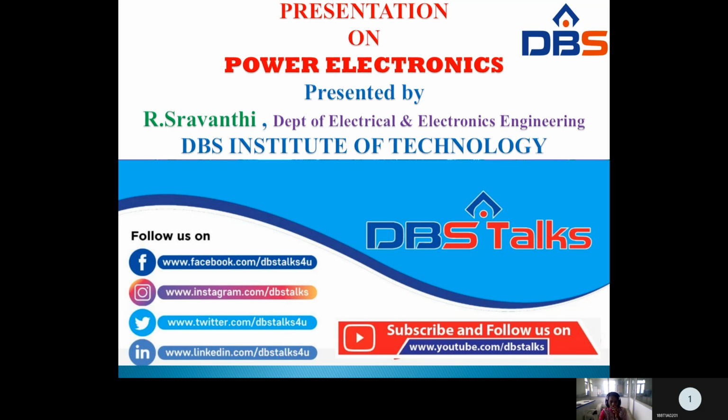So here the capacitor charges up in the positive mode. When the capacitor is charged in the positive mode, a gate pulse is applied to the SCR. When the SCR is triggered, the resulting current has two components. The load current flows through the RL load. This is ensured by the large reactance in series with the load and the freewheeling diode clamping it.